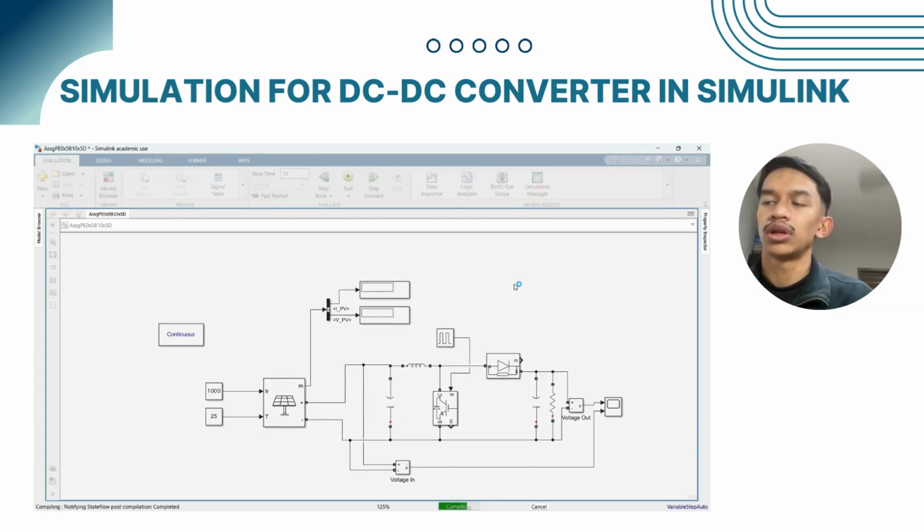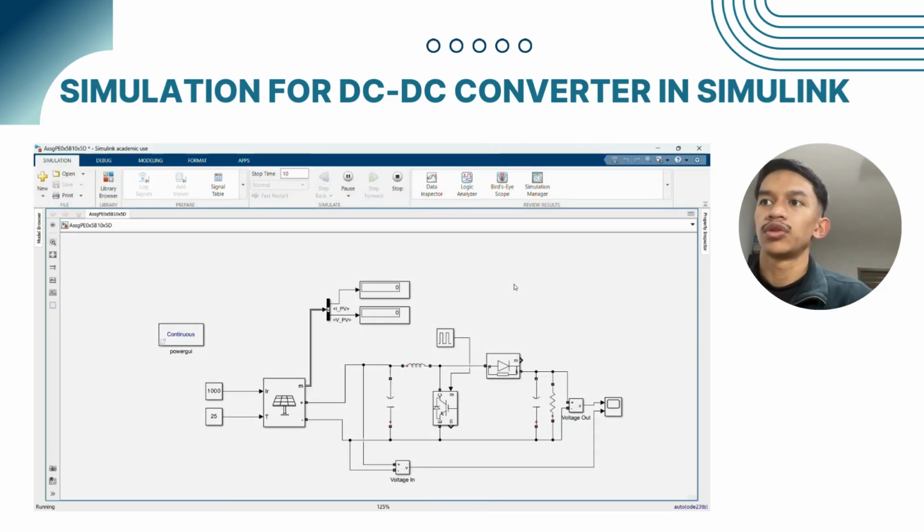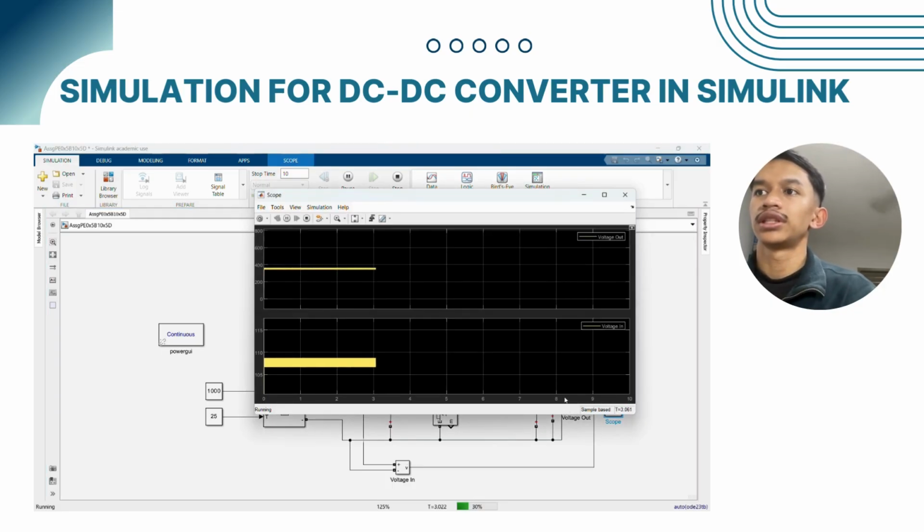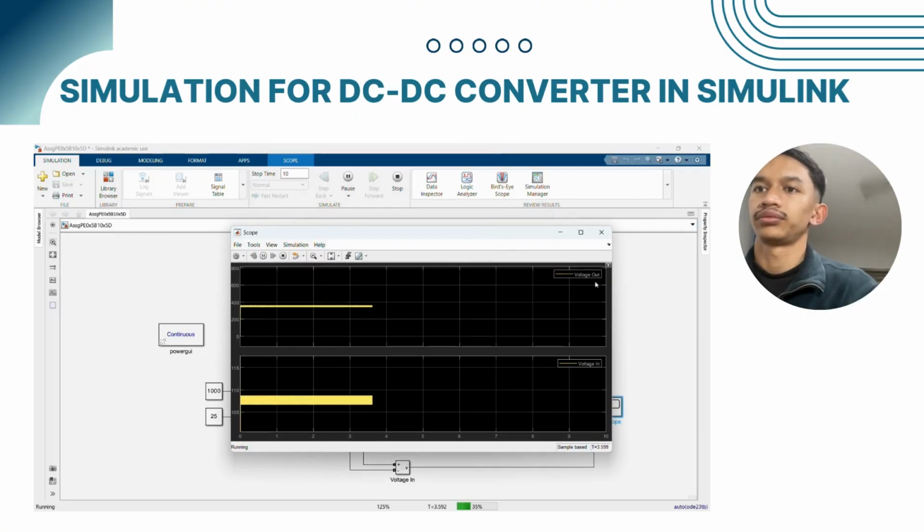Inductor is set to 1.85 millihenry, output capacitor is set to 0.96 microfarad, and line capacitor is set to 0.69 microfarad. We add a resistor value of 288.79 ohm at the output so that the values for the simulation are close to the calculated values.